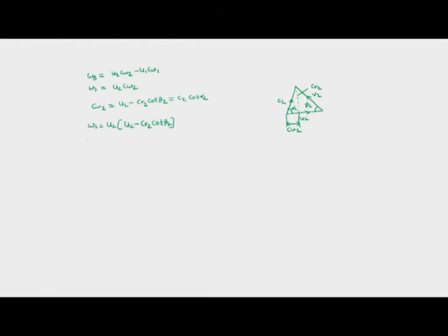Okay. Now we can take U2 common in the stage work formula. Whatever we are writing here, we are not considering any slip factor, and we are also not considering any power input factor. So U2 into U2 into 1 minus CR2 upon U2 into cot beta 2. So stage work is equal to U2 square into 1 minus phi 2 cot beta 2.